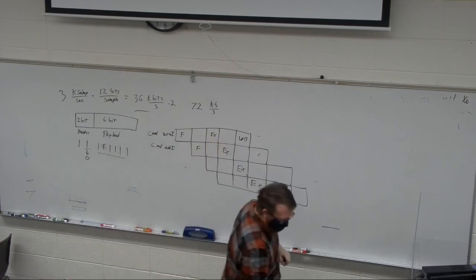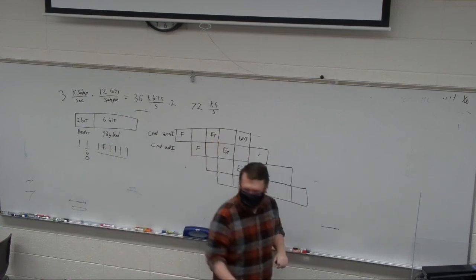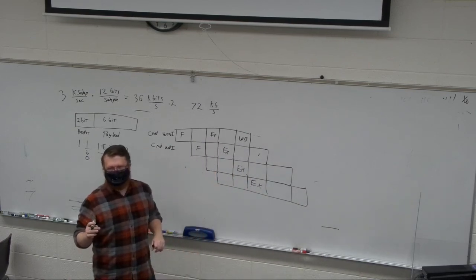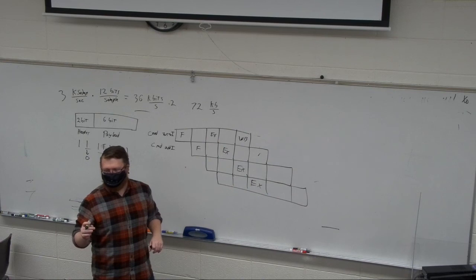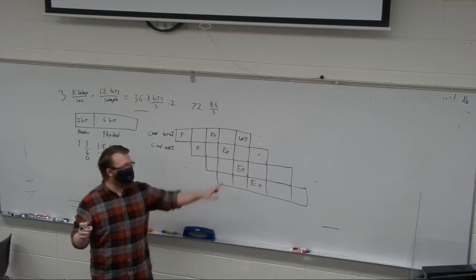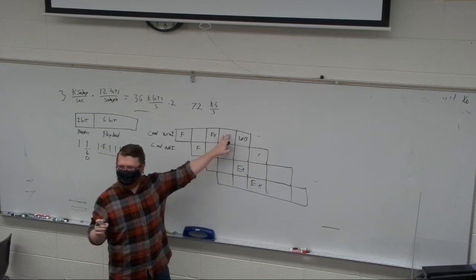Arithmetic and logic can write the computation result to the destination register. Branch instructions must examine their condition and decide to take the branch or not. Load instructions, a memory operation is initiated. For memory store instructions, the data from the second source register is steered to the memory, and a memory write operation is initiated. Yeah. So does anyone have the notes from last time on what I called this stage?